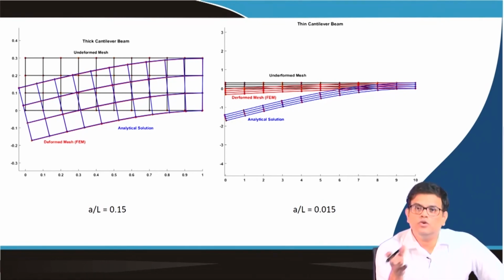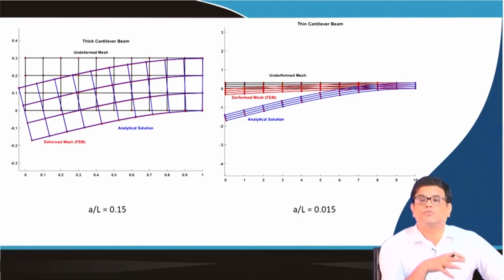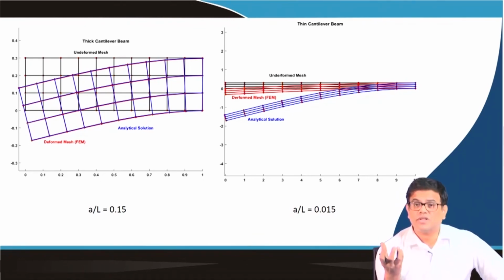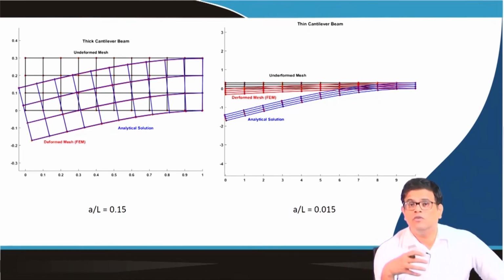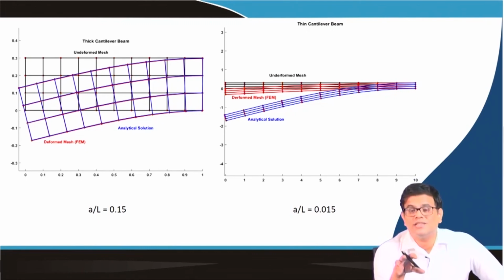Then I will be integrating the bending modes, but neglecting the shear stiffness. So that will give me a better result compared to full integration. Because of this spurious shear, known as the parasitic shear, this mesh locks, and the finite element solution will not be accurate compared to the exact results.